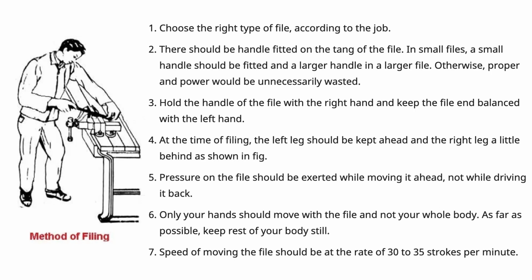This is about how to maintain a file, which I have mentioned in the previous videos also. I'll say again on the application of the file. A file should be used for giving final finishing touches to a job of metal or wood, but we'll use metal here in our field. After chipping, a job of metal generally becomes rough, and the file is used to make it smooth. In case of a machine, the part is larger in size, and then the required size of file is used to make it suitable. In addition, a file is used where other cutting tools cannot be used, and files are also used for sharpening the edge of some other cutting tools.